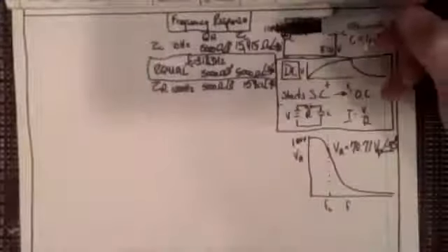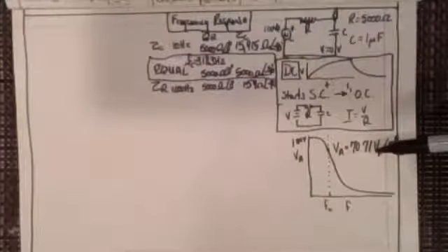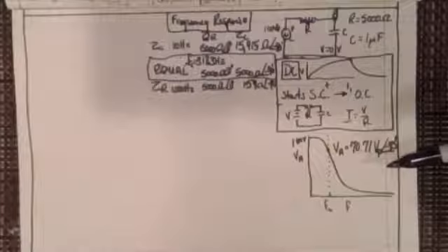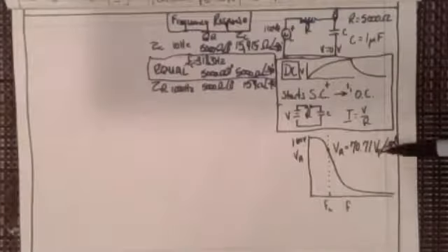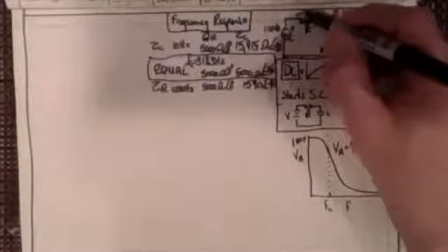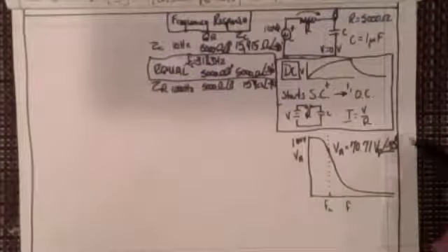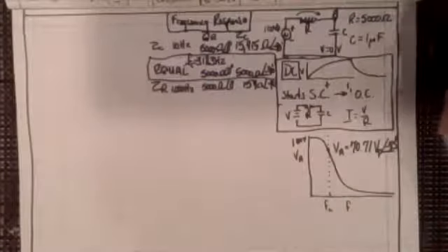Although the RMS value for 100 volts peak would be 70.7 volts, wouldn't it? But this is 70.7 volts peak, and that's what's happened because there's been a voltage drop across the resistor. And that's why it's now 70.71, and it's at a minus 45-degree angle.